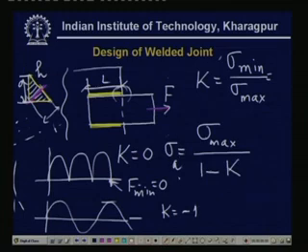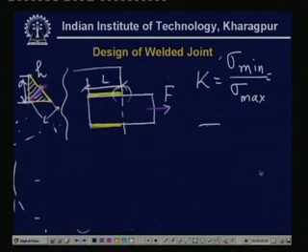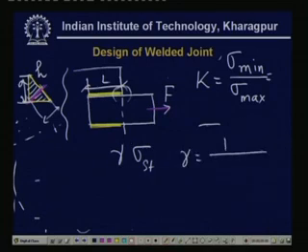This is the allowable stress, and the maximum stress here should be lesser than this allowable stress. In Russian literature, of course, the procedure is a little complicated. Again we calculate the static stress, that is the maximum value for the static loading, and multiply by a factor gamma. It looks a little complicated.